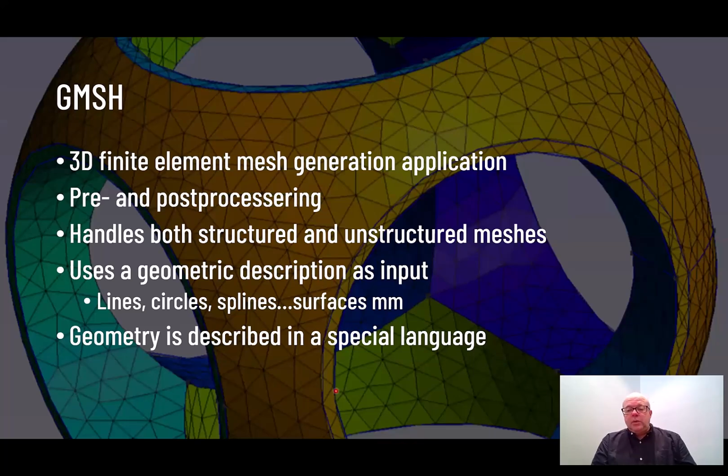It's also a standalone application. So if you open a command prompt and type GMSH, you will get the user interface for that application. You can also model in that application, so you can create geometry and then create mesh, and there is also an interface to solvers as well. And it can do both structured and unstructured meshes.